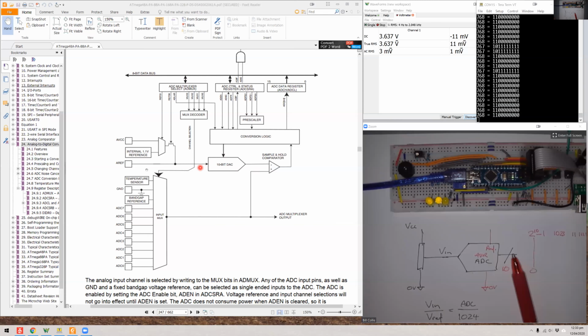What we'll look at is where we're getting our reference voltage from. And our reference voltage comes from this AREF pin on our microcontroller. So where does that come from? Well, we've got a number of choices. We can actually connect something to that pin ourselves as a reference voltage, as long as it doesn't exceed VCC, we're okay. Or otherwise, we can use some of the switch logic from REFS0 and REFS1 bits inside the ADMUX register to turn on whether we're going to use the AVCC as a reference voltage, which connects this. Otherwise, we could use this 1.1 volt internal reference voltage.